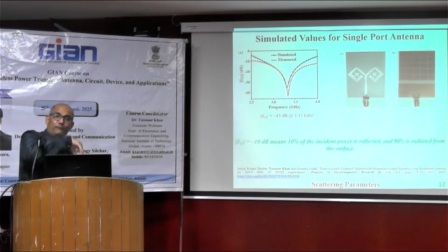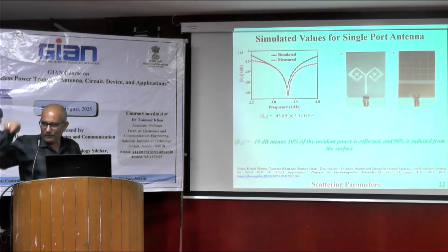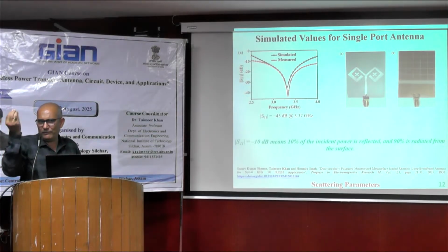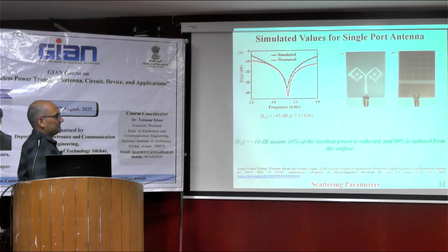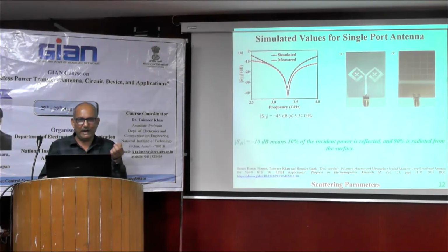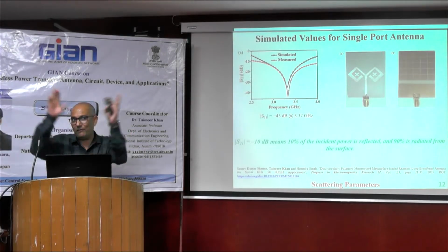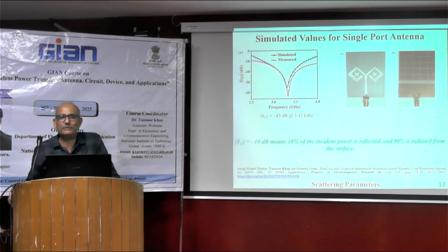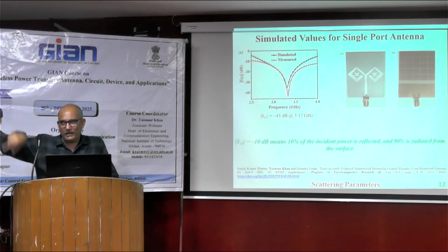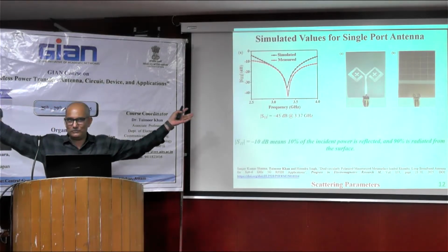If you try to convert that into linear scale, you will realize how minutely the values are changing in linear scale, but you will observe a drastic behavior in the logarithmic scale. Minute variations in bigger scales, as well as bigger variations in minute scales, are both very easy to represent in dB. 35 dB to 40 dB is only 5 dB of variation, but if you convert that to linear, you will see a huge difference.